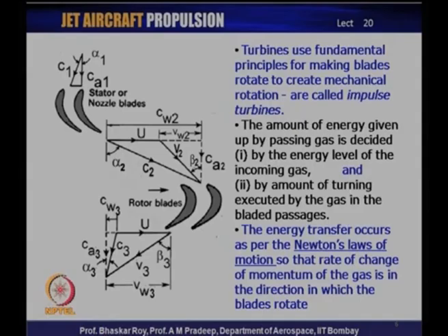Now, to create high temperature, you have to burn more fuel, or you have to have a bigger combustion chamber. Now, if you create higher and higher temperature, it is necessary that the turbines withstand that temperature. Now, we understand that if it has higher inlet temperature, it will produce more work. That stands to the thermodynamics that we have done. It stands to the fundamentals that we are discussing right now, and we shall see later on that if you create high temperature, it can indeed do more work, and that to do that you need to probably create cool turbines.